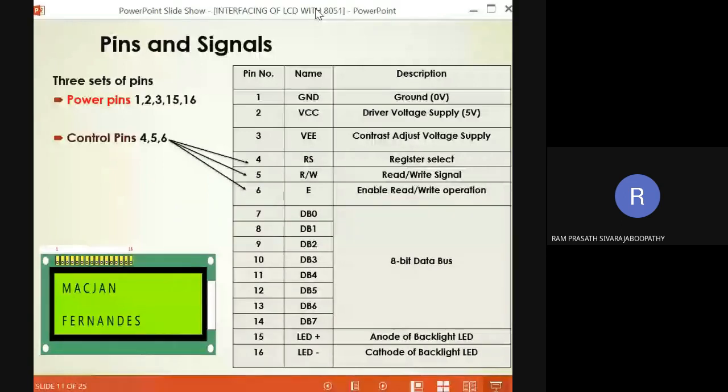You give the LCD clear command to the LCD panel, the LCD driver. Will the clear operation happen instantly? Yes or no? Once you issue the LCD clear command, it takes some time for the operation to be completed by the driver IC.